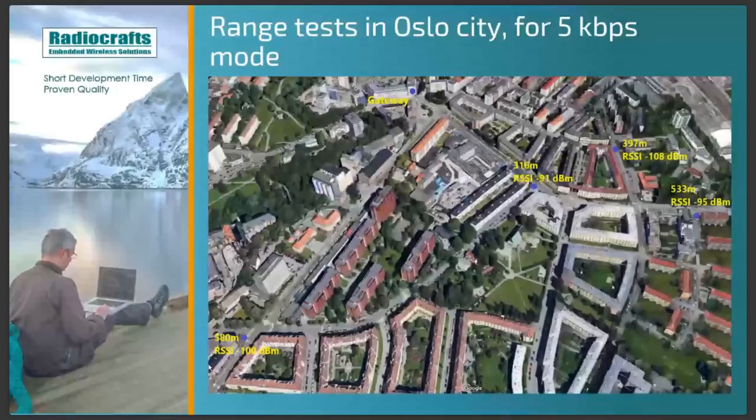The sensitivity of this radio is actually minus 120, so in a noise-free environment we should be able to receive down to minus 120 dBm. But this test stopped around minus 100 dBm, and that is due to the background noise we see in the office, and the LTE base station on the building next door is one of the key factors in our evaluation of that.